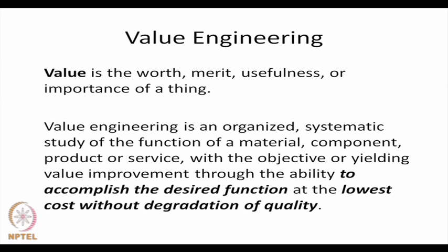What we mean by value is the worth, merit, usefulness or importance of a thing. So, how a product is useful to the customer. It is not just at what price this usefulness has been derived. So, it is the worth divided by the cost which is equal to value. So, if cost is low, the value is high, and if its usefulness is high, value is also high. So, in value engineering, we try to give the same utility to the user at a minimum cost, and that is value engineering.